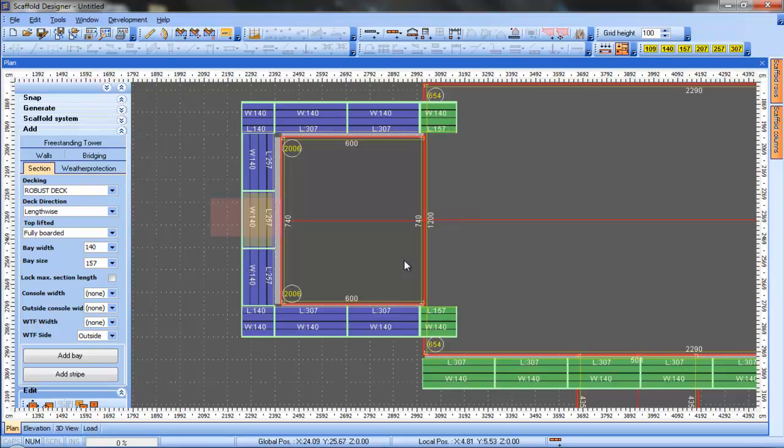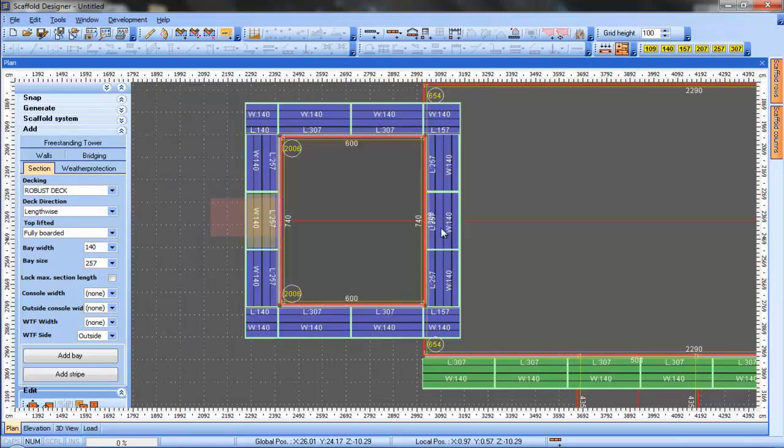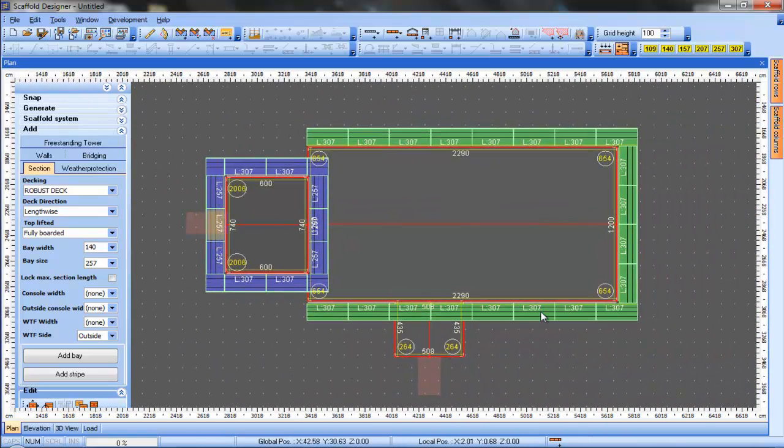We'll take sections from the front to make the clock tower symmetrical and place them as needed. At the moment we are intersecting with the roof, but we will adjust the sections accordingly until they are all placed. Now that the sections are all placed, we will select them by pressing the Control key and the Shift key at the same time. And now everything is ready for the creation of the scaffold.